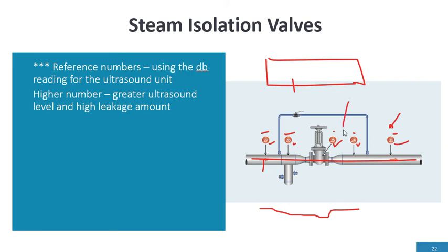If this valve measurement is equal to or less than my upstream measurements or my downstream measurements, the valve is seated and not leaking through.